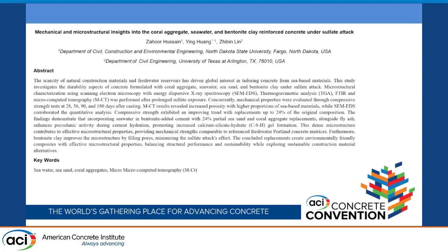To analyze the performance of concrete, we used mechanical performance testing, such as compressive strength at different ages of concrete under sulfate attack, under sulfate environment, at 28 days, 56 days, 90 days, and up to 180 days. We performed microstructural analysis such as XRD, SEM-EDS, FTIR, and TG analysis, along with some hydration studies to analyze the overall microstructural performance of bentonite reinforced concrete.